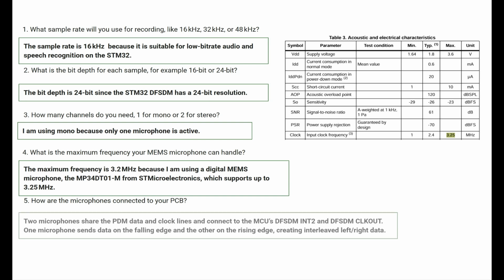The fifth answer is that two microphones share the PDM data and clock lines and are connected to the MCU DFSDM channel 2 and DFSDM clock out. One microphone sends data on the falling edge and the other sends on the rising edge, creating interleaved left and right data.